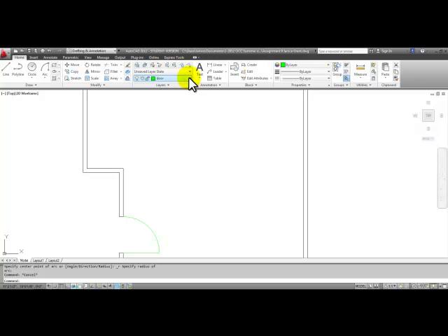We're ready to draw our demolition line, which is the hidden line that goes across this floor plan. I'll go ahead and make the demo layer current. And remember, we set up the demo layer as a hidden line. When I start the line command, I'm going to click this corner inside face, pull my mouse over to the other wall and click. Right click and pick enter.